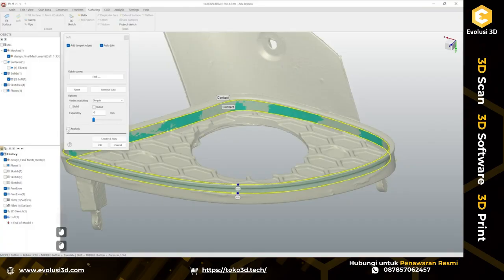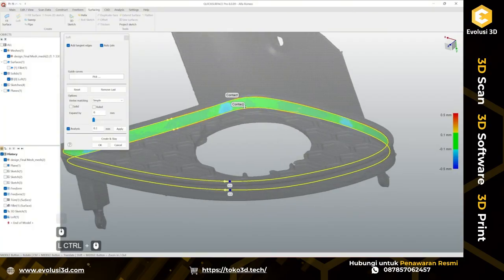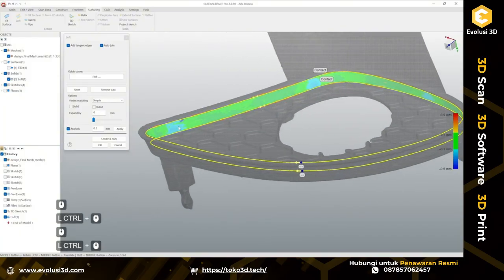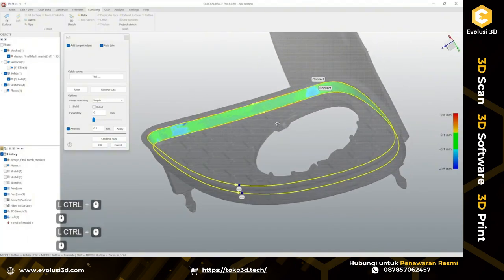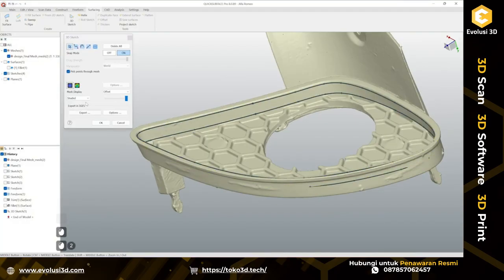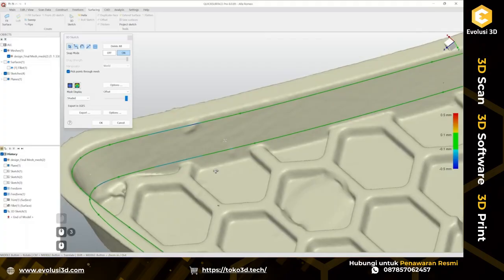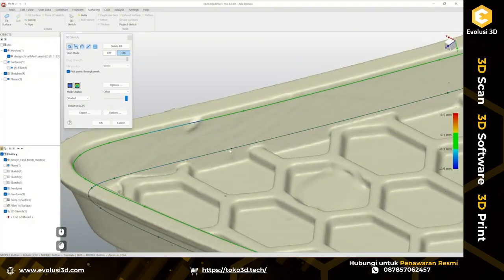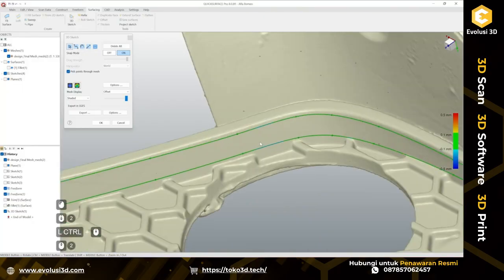Once we're satisfied with these 3D curves, we can accept them and go to our loft window, select both of them. Let's see the analysis. Okay, so we're pretty close. Probably we want to make some adjustments in some places here to make everything nice and green. In order to do that, again, we're going back to edit our 3D sketch.